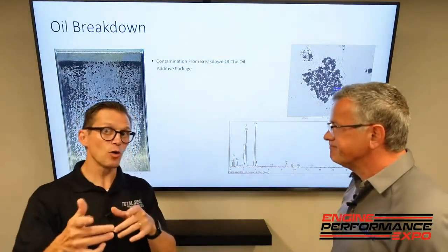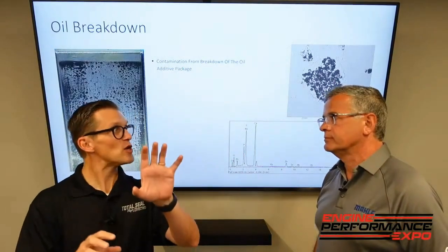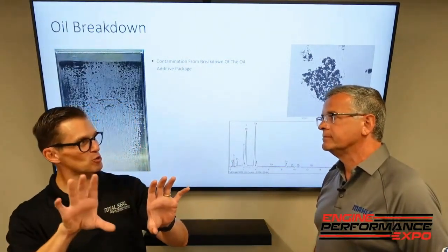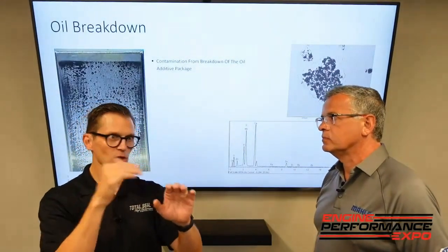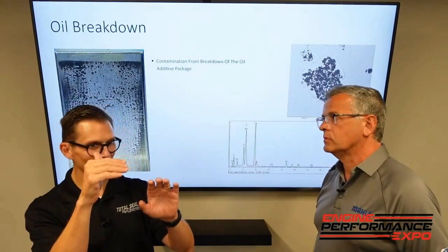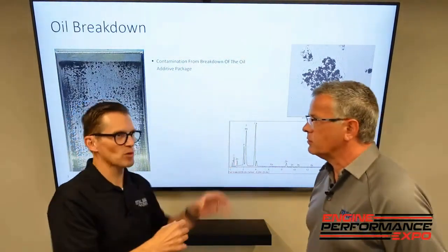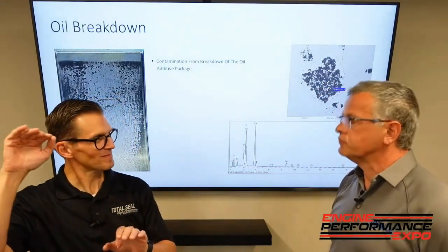Yeah. In fact, in used oil analysis, that's one of the things we recommend to do is, look at the new oil first. Compare the additive levels to your used oil. Because what you'll see sometimes is, before there's a problem, you'll actually see the additive levels beginning to deplete. It's consuming the additive package while it's running, and that normally precedes that increase in wear metals.